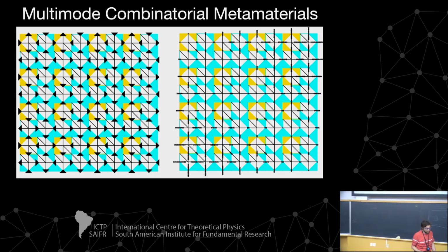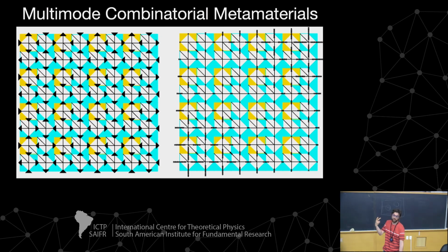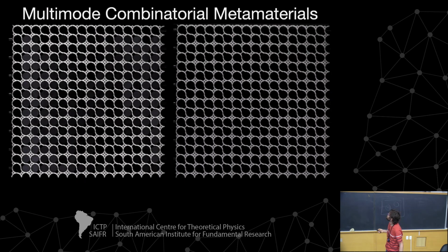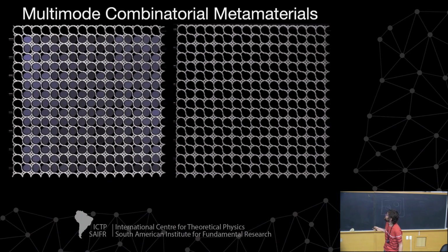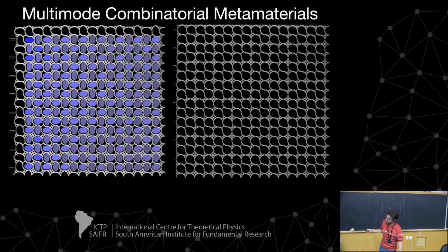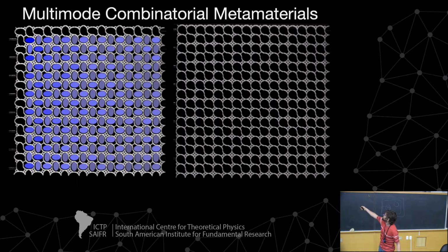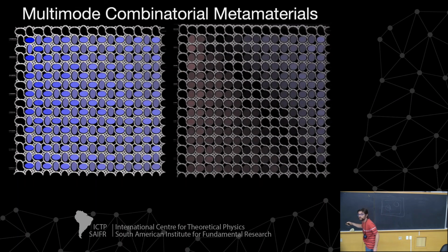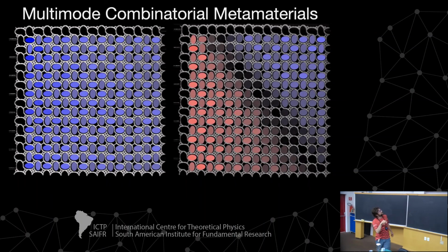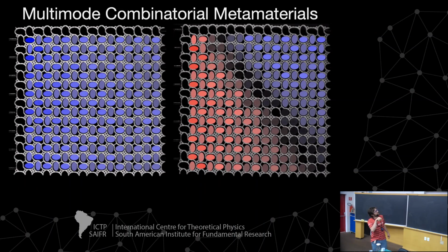That means that with one lattice you can have 2 responses. You can print it, and decide to actuate one mode by pushing with fingers on the side. Here I color the ellipticity of the pores to make the deformations more apparent. You see that this is the first rotating square mode, and this is the other one that has this change of ellipticity across the diagonal.